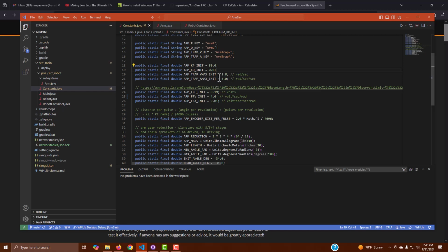The 1.8 radians per second for the velocity, that's kind of important that we get that right. You can't just specify any value that you want here. The arm has to be able to actually move that quickly. And so I'll show you in just a second how you can see what that maximum really is. Acceleration, there are some limits, but they're not as clear cut, and you might have to evaluate what the maximum acceleration is.